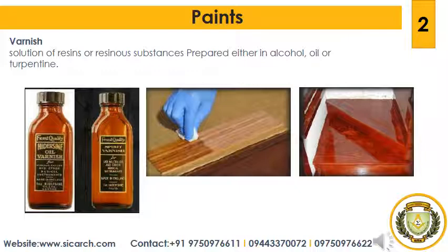The oil varnishes dry very slowly but they form a hard and durable surface. In fact, they are the hardest and the most suitable varnishes. They are specially adopted for exposed work which requires frequent cleaning. They are used on coaches and fittings in houses.